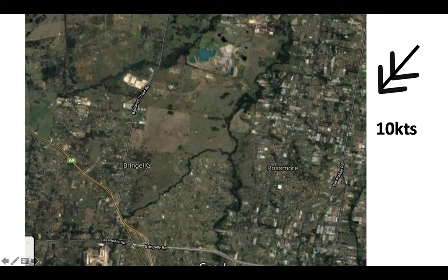Shape is, if you land diagonally, kind of rectangular. Slope is relatively level. I've flown over this field, so I know what the slope is. Size is sufficient, more than 500 meters. And surroundings: we've got a few rocks and trees we need to avoid.